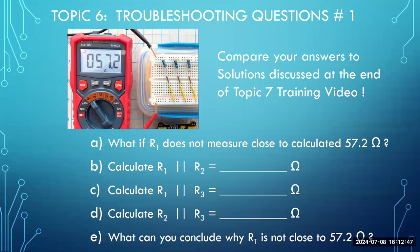So yes, we could not measure 57.2 ohms, possibly if one of these was incorrectly pulled out. If you're not sure how to read the resistor color codes, you can always rely on your multimeter to make sure these are in fact 100, then 220, then 330 ohms. What else would be possible? If, let's say, you measured the three resistors and they were as you wanted, a 100 ohm, a 220, and a 330 ohm resistor. They are the right ones.